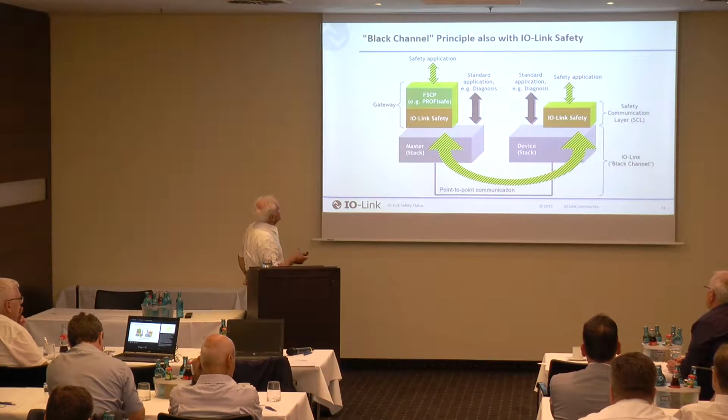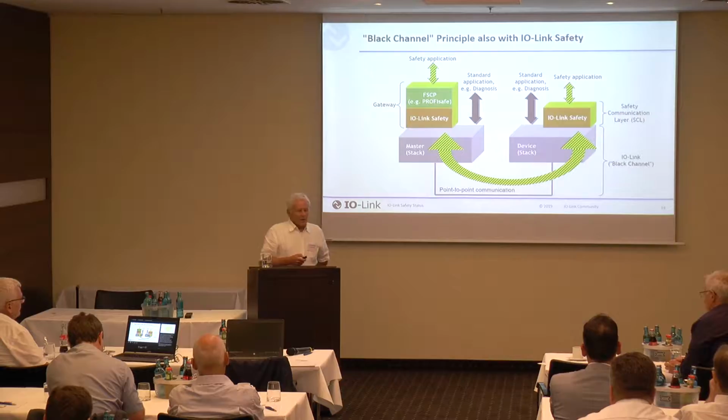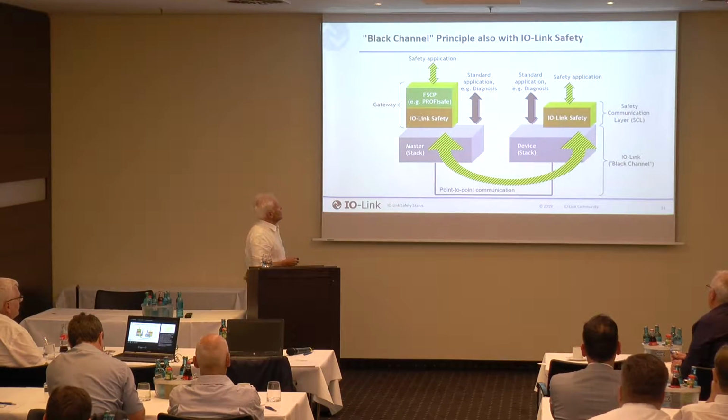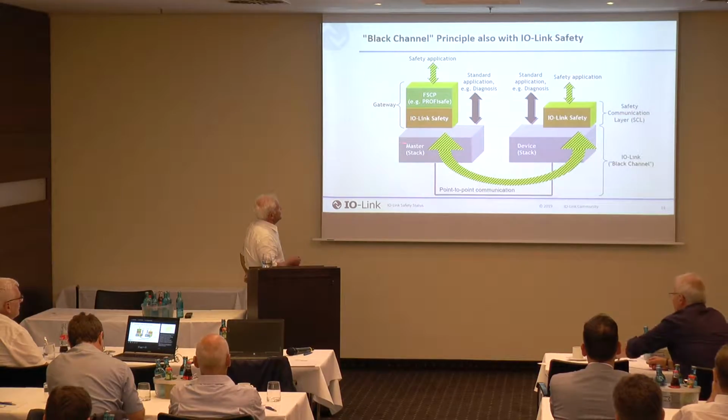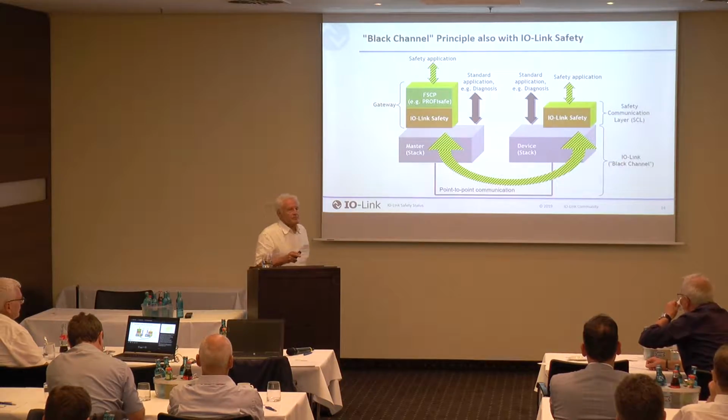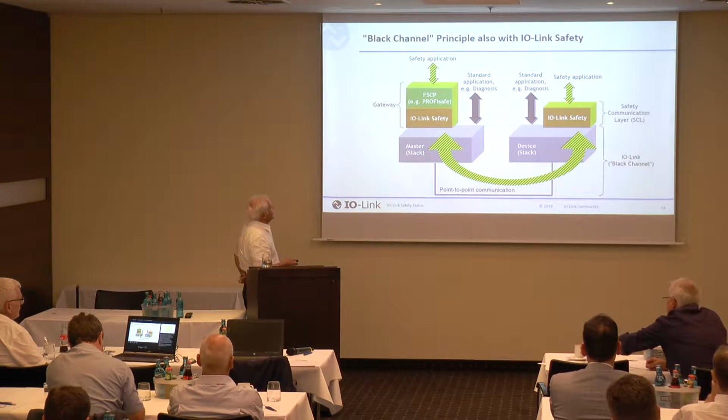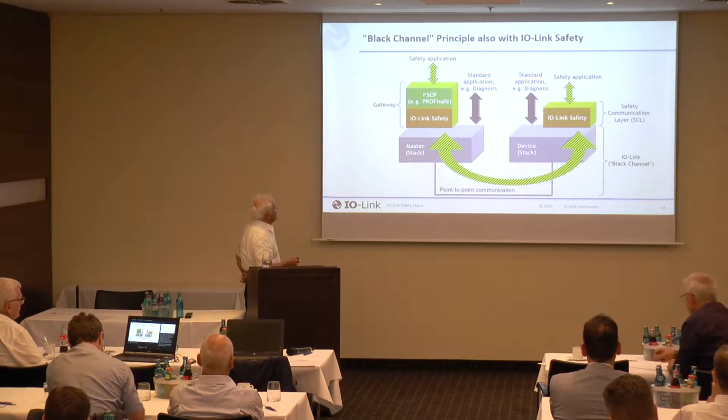The principle is following the black channel approach. So we do not need safety here on this normal IO-Link level. So it is untouched. And we put a layer on top of these layers here on the communication layers. That's the principle.